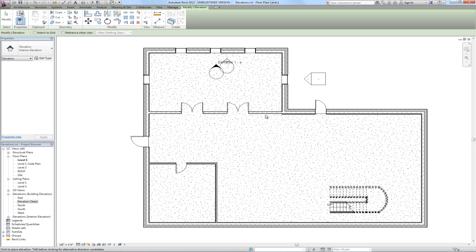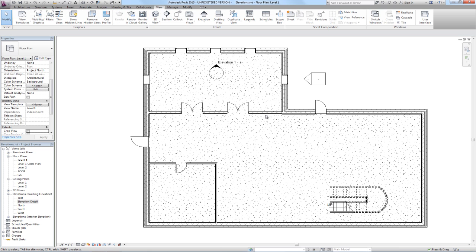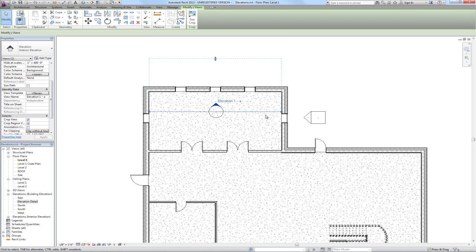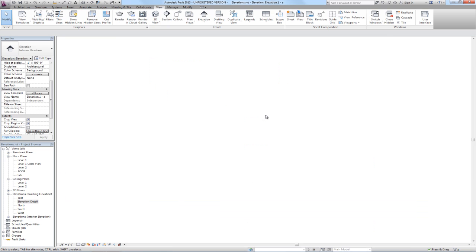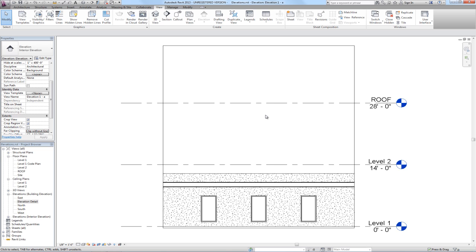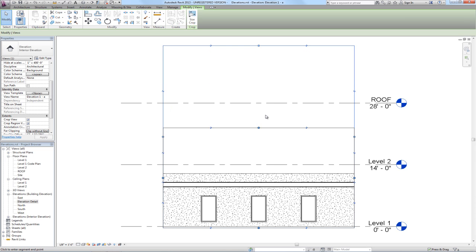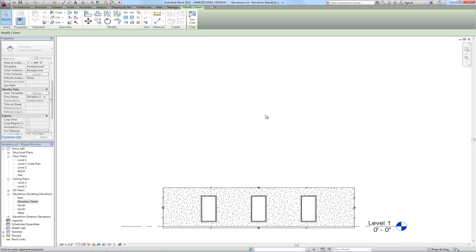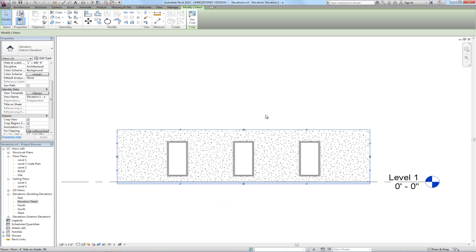So we'll go ahead and click, pointing at the north wall in what we'll call a loading dock area. If we select the pointing part, we see again that the extents went out to the adjacent walls and just past the wall that we're looking at. We open that interior elevation and we adjust the crop region down to match the underside of the floor structure above. If we had a ceiling in this area, the crop region would have gone up to the underside of that ceiling automatically.